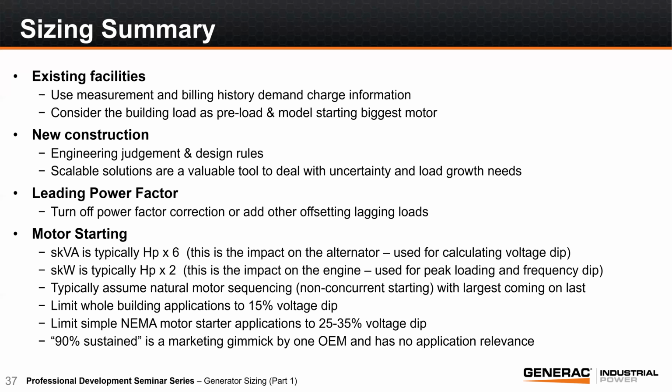The biggest thing on the fire pump is that you want to make sure you're maintaining a 15% or lower voltage dip. You can't go above 15% on the voltage dip for your fire pumps. That is the biggest consideration when you're doing that sizing. As far as a garage or any other standard building, if you're looking at a garage door, that would be considered like a motor. So you would size based on using it as a motor. In general, those would be the biggest factors, especially for a fire pump.